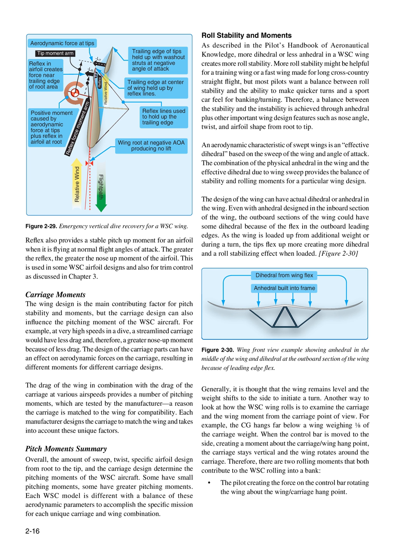Reflex also provides a stable pitch-up moment for an airfoil when it is flying at normal flight angles of attack. The greater the reflex, the greater the nose-up moment of the airfoil. This is used in some WSC airfoil designs and also for trim control as discussed in Chapter 3.